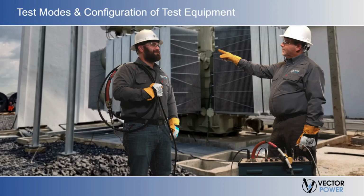Test sets that perform the dissipation or power factor measurement can utilize two low voltage measurement channels or leads and also a ground lead simultaneously. Although there are several manufacturers of dissipation or power factor test systems, we will use the Doble Model M4100 as our basic model in this presentation today.